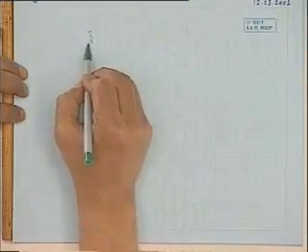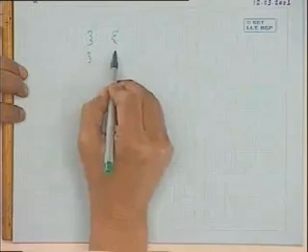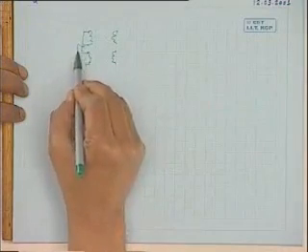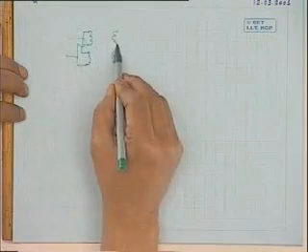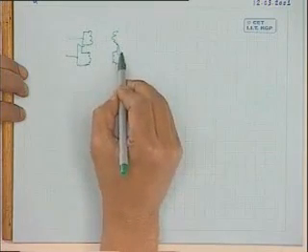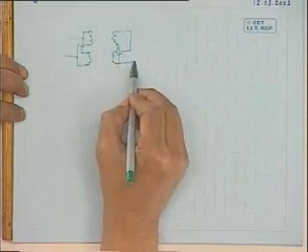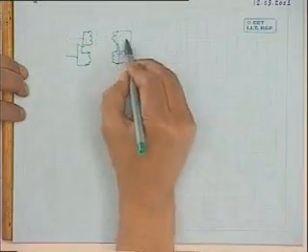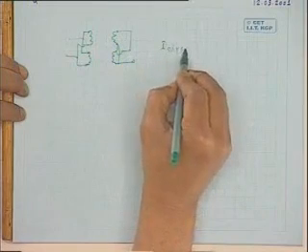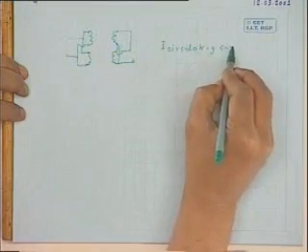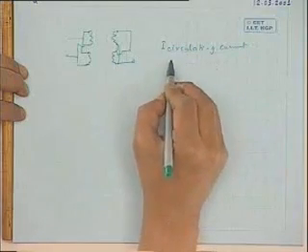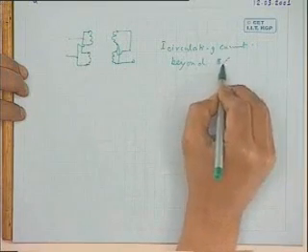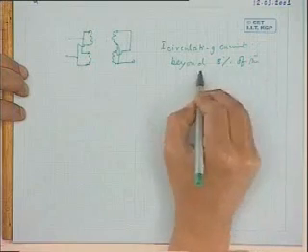Are you getting? Suppose you have taken two transformers and made them parallel, and the secondary side also you have made parallel. The moment you make them parallel, there will be circulating current here because a difference of voltages will be there. That circulating current should not be tolerated beyond a maximum of, say, 8% of the rated current.